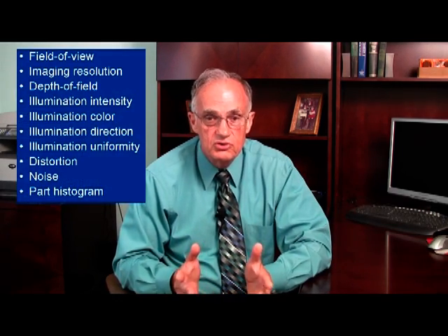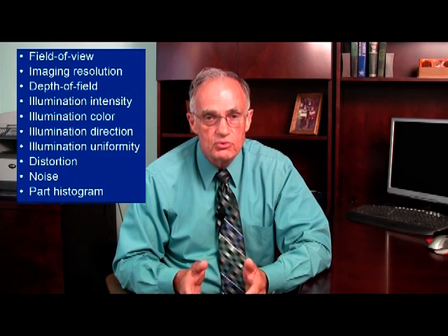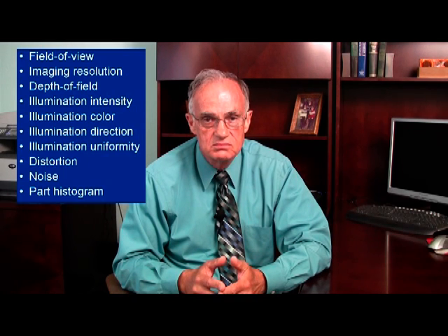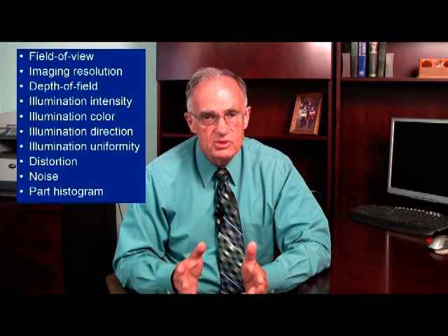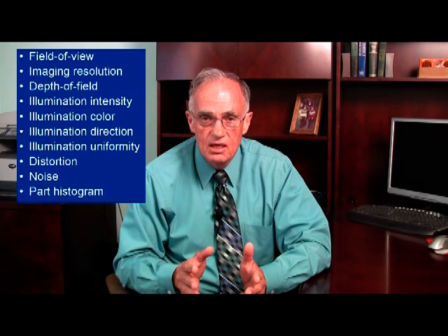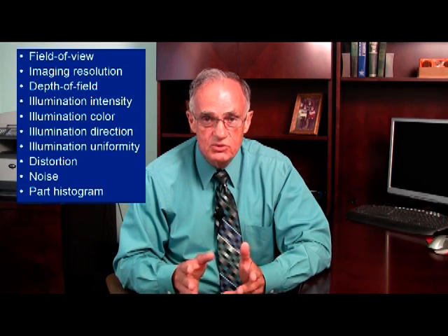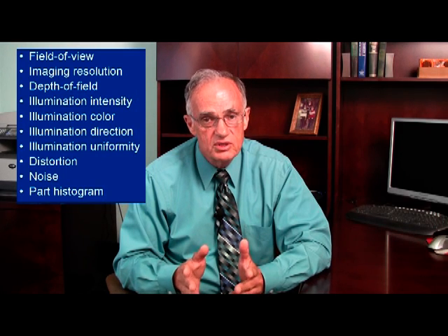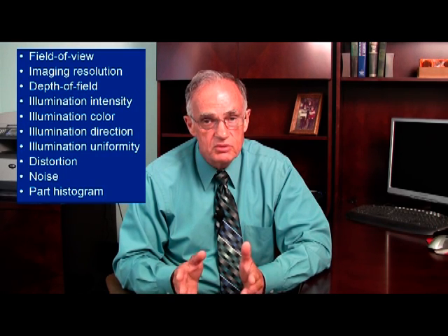There are 10 measurements that you can make on the imaging system that I call benchmarking the imaging. There are 10 parameters that you should benchmark that will allow you to recreate your imaging. Now, sometimes you don't need all 10, and sometimes in specialized situations you will realize one or two additional parameters that you should benchmark to keep your imaging under control.